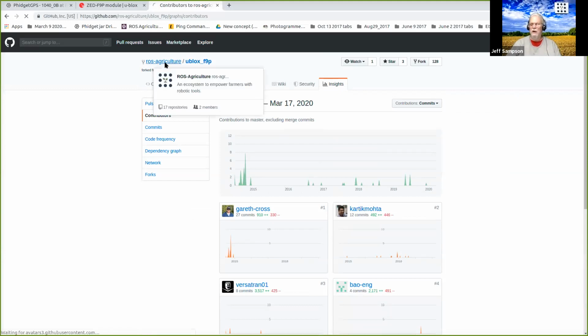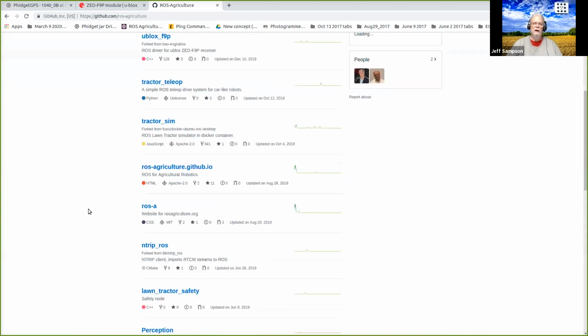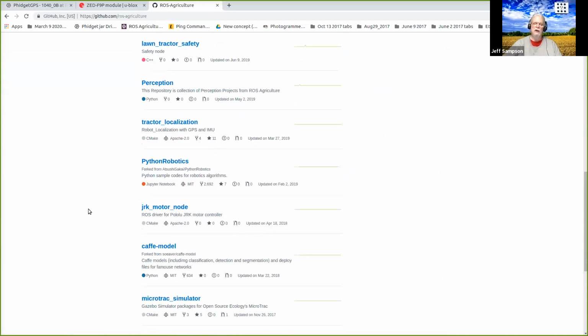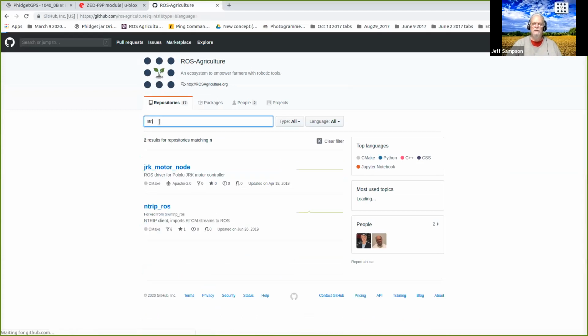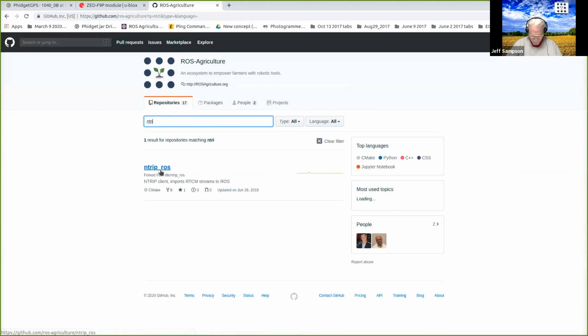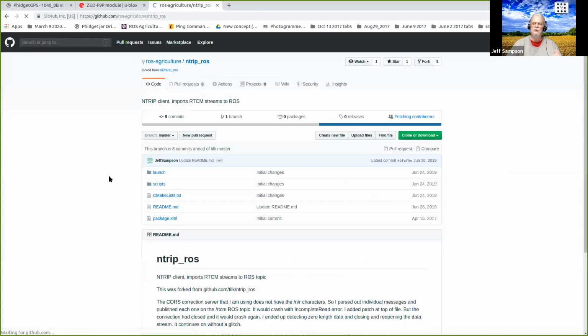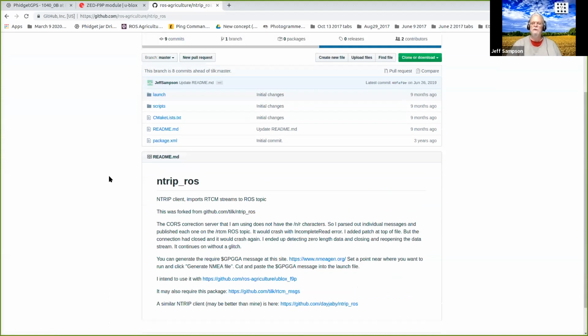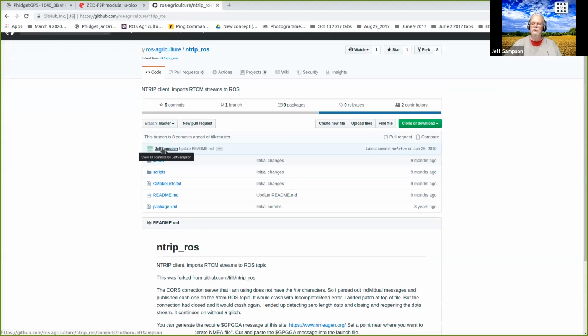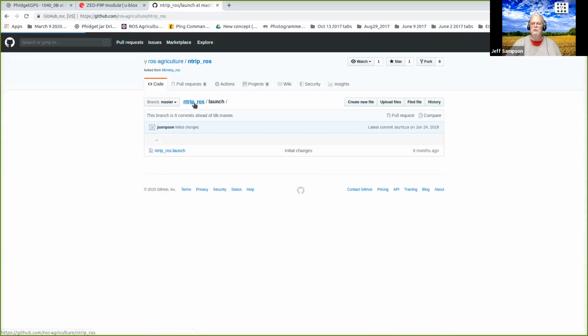So I went and found somebody's code, and it's a ROS node you start up, and it will connect to your DOT site and grab the data and publish that as a ROS topic. So then I had to hack on the driver for the F9P itself. I put like 5 or 6 lines of code in that to subscribe to the RTCM data that I'm publishing, and then it sends that over the same USB cable. So I just have a single cable between the GPS receiver and your ROS machine, and it sends the correction data out to it, and it receives the position data back all over the same cable.